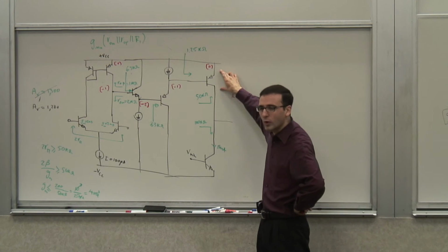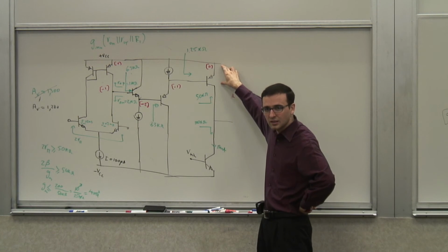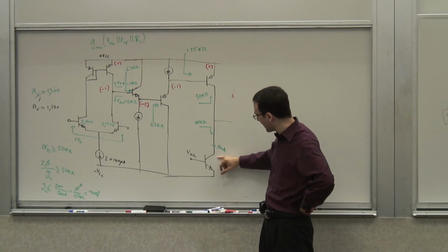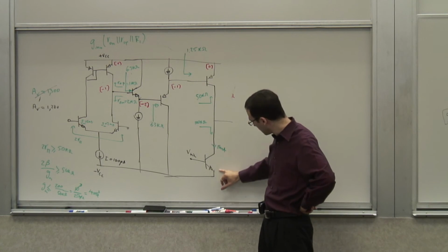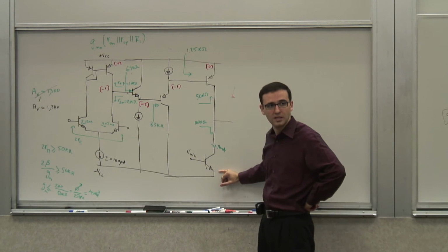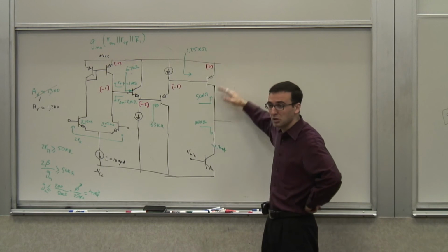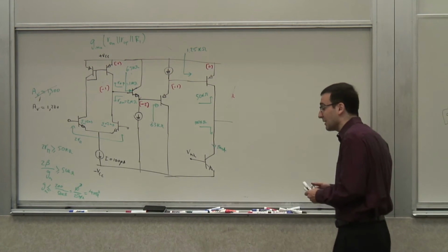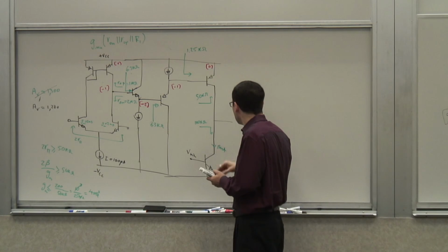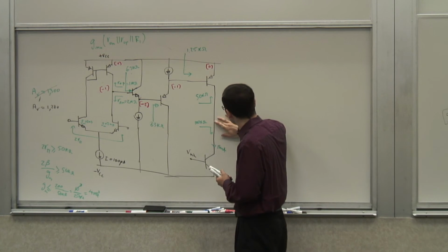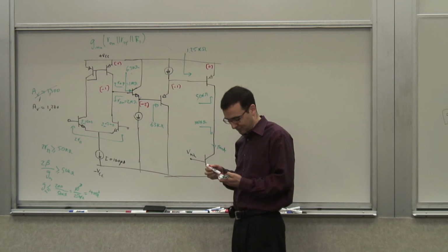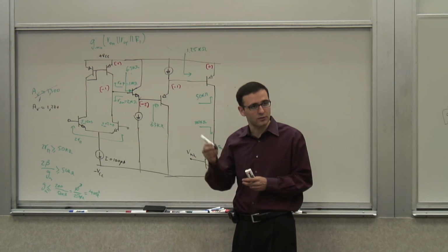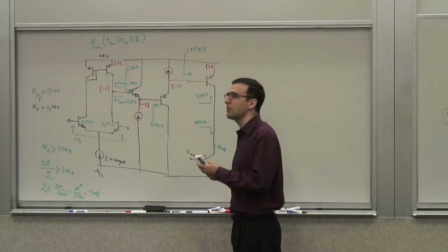So, it can be about 0.2 volts below VCC. And on this side, the same thing, because this guy is basically a collector. It can go as low as 0.2 above minus VCC. So, this guy has reasonably large swing, right? So, I can maintain that. If I can maintain that, that would be nice. But let's worry about getting the gain there first, and then we'll worry about the voltage swing at the output. So I need 2 buffer stages, right?